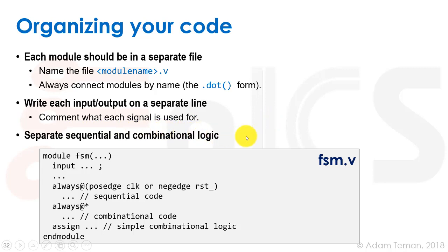Some people like to make these big sequential blocks that have a lot of stuff going on. From my experience, each and every flip-flop is very important. You want to have personal knowledge of every flip-flop. You want to check that it was synthesized how you intended, what came out, and so forth. You want to be friends with the flip-flops. Give them their own always block.